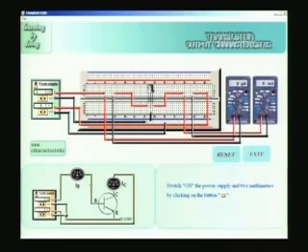Now there are two multimeters on your right. The first one is measuring the base current. If you follow the two wires, you can see it is connected with the base supply, and it comes in series with the base and emitter junction of the transistor. Similarly on the collector side, I have one more multimeter used as an ammeter, a milliammeter, for measuring IC, the collector current. So I have the two power supplies and two current meters, all made out of digital multimeters chosen in the current range.